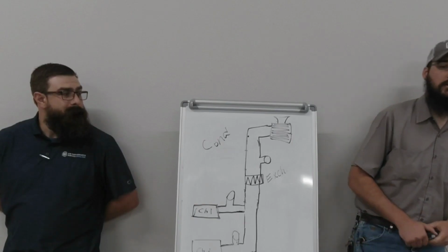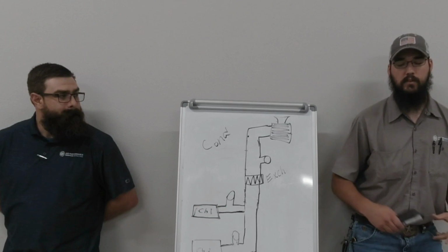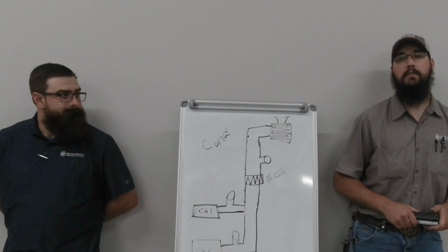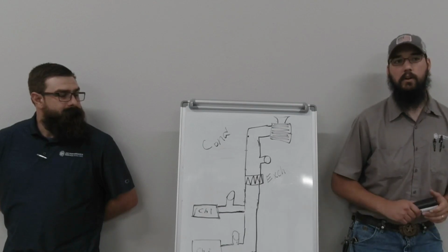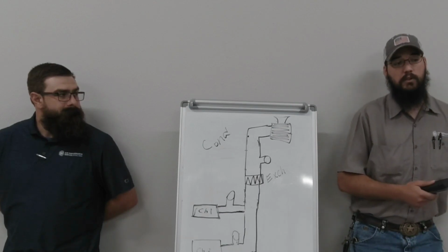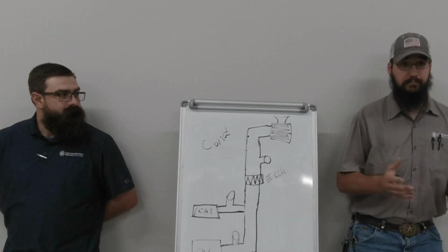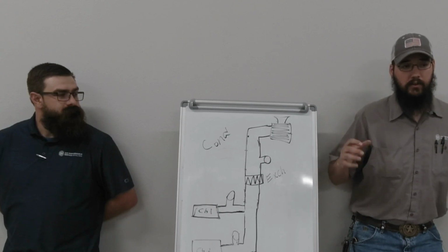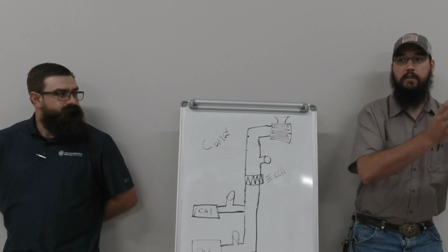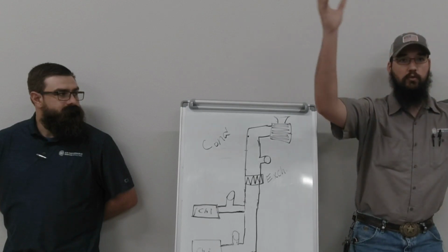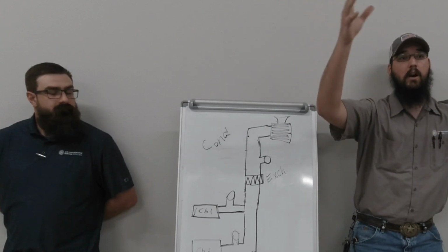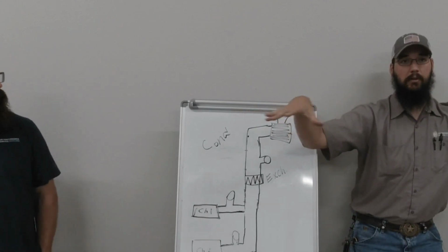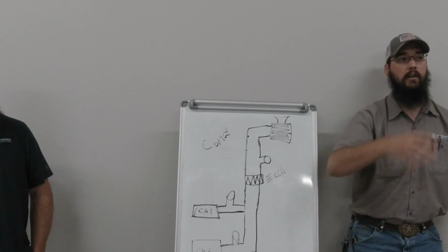I haven't seen it here. There are some larger facilities, it builds off of it. It's a less intense version of the ice storage, where they just have multiple chillers feeding a whole complex of buildings, and all the chilled water gets pushed into this tank. These big, huge silo-looking tanks are somewhere on the property, and then all the loop pumps for the complex will pull water out of these tanks.